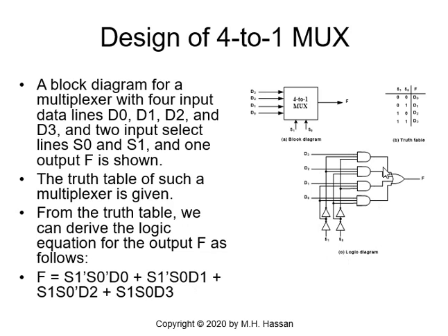The implementation of the circuit is quite simple. You see it here, with the corresponding data lines. So we can generate this circuit easily and implement it. We just need a 4-input OR gate because we have 4 product terms here. And this is a sum-of-products formula, which can be implemented easily with any type of gate, especially NAND gates if we want to.